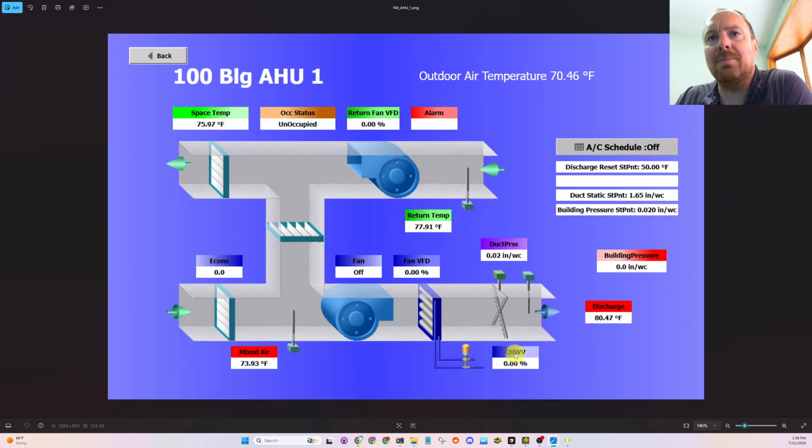And then we'll also want to see if the chilled water valve is leaking chilled water, which would cause really low discharge air temp if the fan is on. It does happen in aged systems, really old systems; these valves' performance degrades.